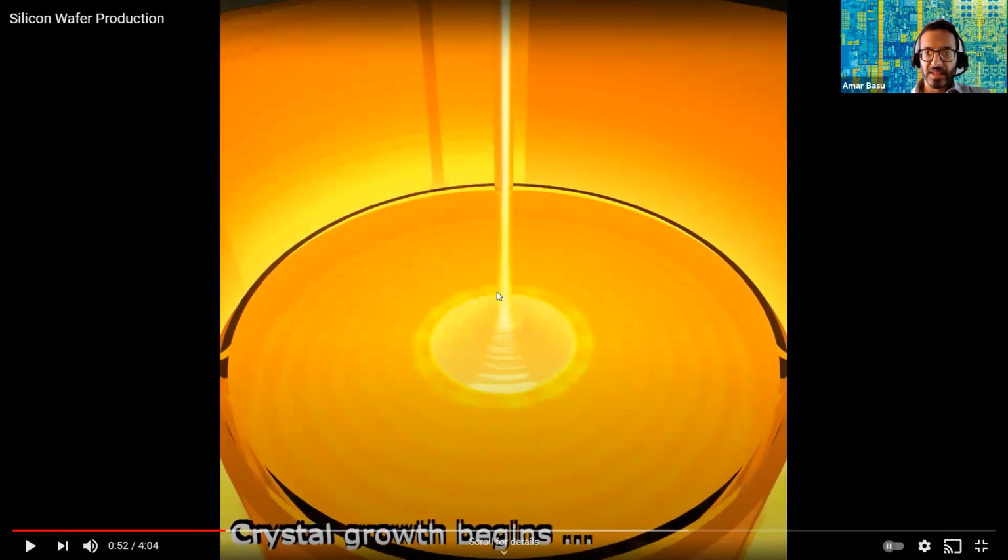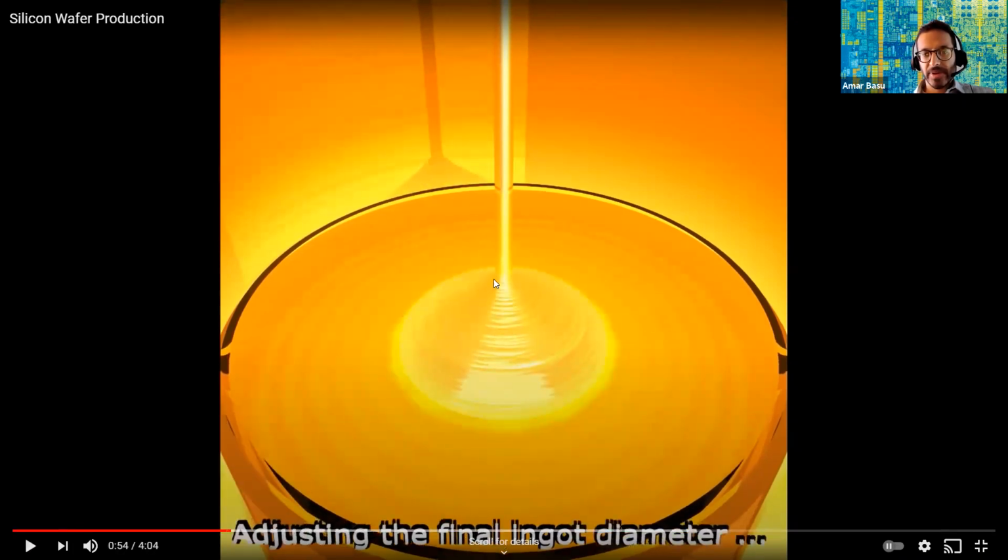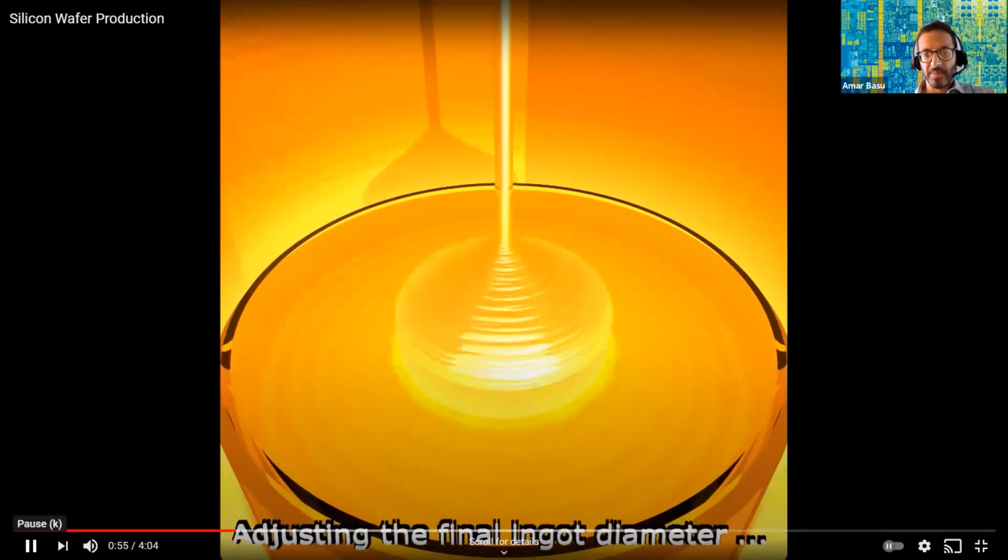If we watch this again, you'll notice this spindle is spinning at a very specific rate, and it's also being pulled out at a very specific rate. Actually there are three parameters: how fast the spindle is spinning, how quickly it's being pulled out, and the temperature of the melt. As it's pulled out, you can see this ingot magically appearing.